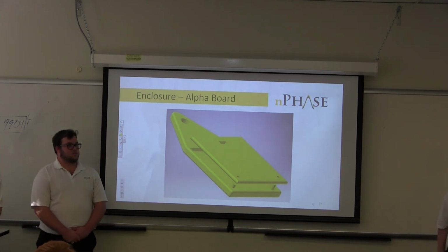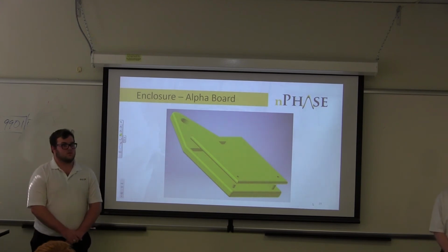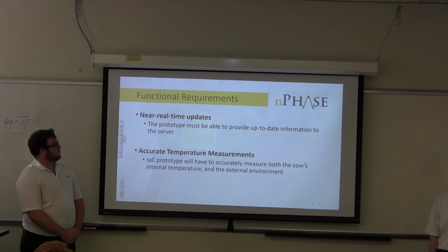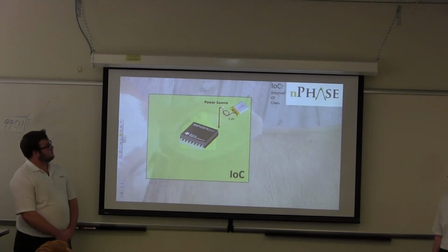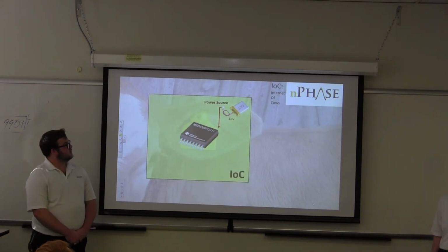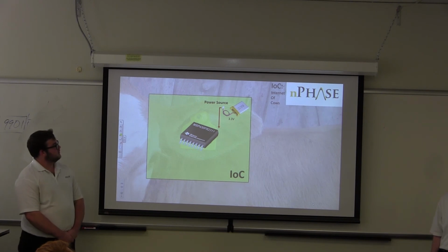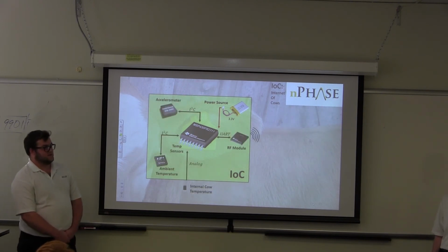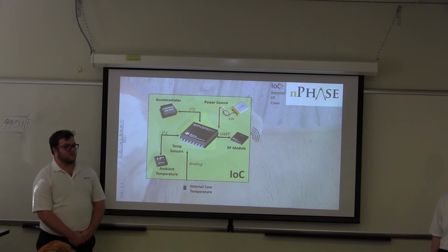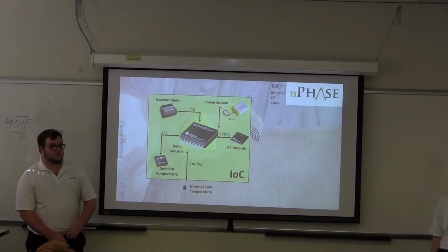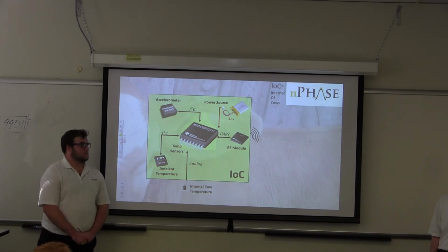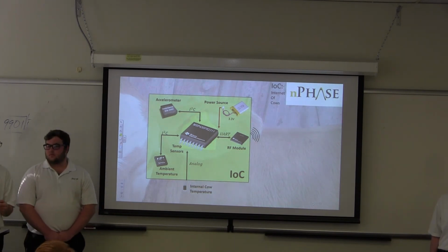So for your power, if you want to go back to the conceptual block diagram, is that the battery that y'all are going to be using? Yeah, so the battery we have is 3.7 volts, and it's regulated down to 3.3 for that microcontroller. Then we have 2.0 going to the Wheatstone Bridge, the one that goes to the cascade. That's the actual battery? Yes. And so there's no charge circuitry, so this is going to be a battery that's replaced? Yeah, that would be something they would unplug and charge.